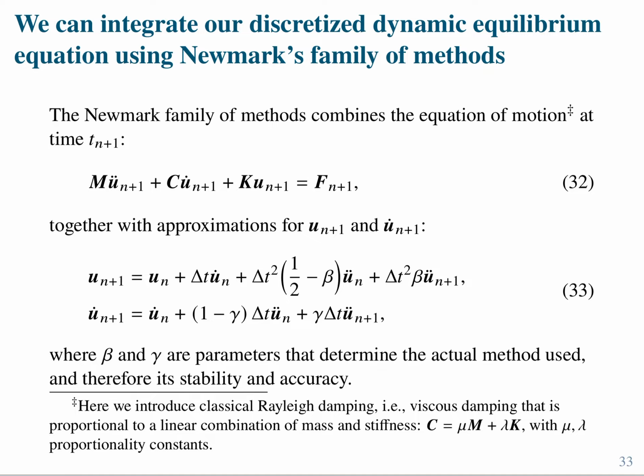Notice that now, for the first time, I'm going to introduce the damping. We're going to do Rayleigh damping, which is viscous damping that is proportional to a linear combination of mass and stiffness, where this mu and lambda are just simply some constants. So this is a way you can introduce damping into the system. And now, well,